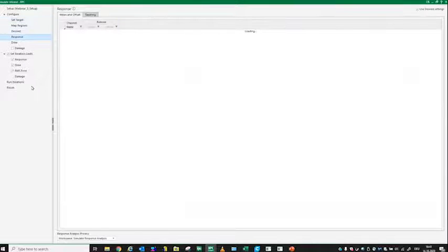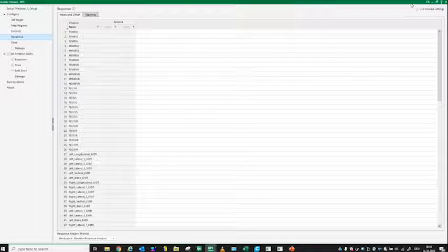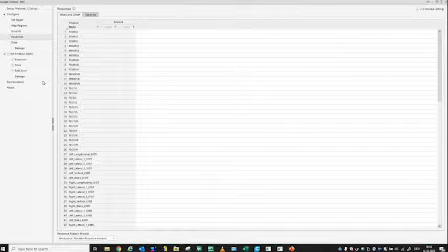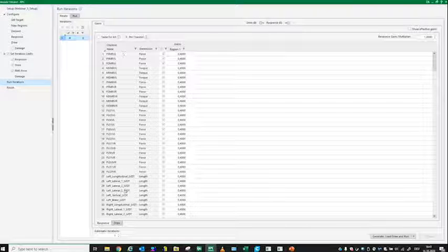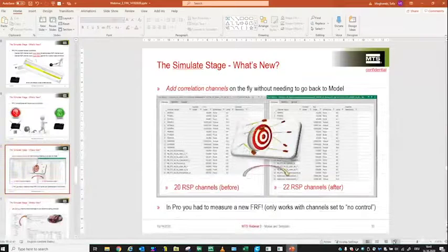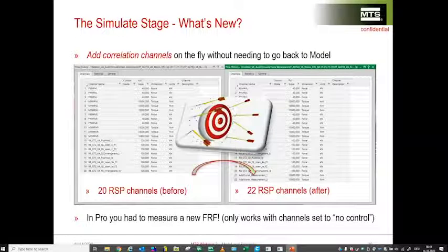And then finally, oh sorry, I was on the wrong node. So finally, depending on the settings I made here, the selection of my channels will show up here. In my case, I have 44 channels here. During the iteration process, I can even switch them, change my target file, switch the channels and still continue with the iteration. One thing to take into consideration is that the target channels must still be a subset of the station response channels. Otherwise, it's not working.